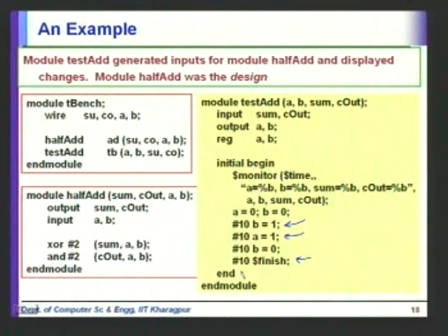Alright. Why do we have this 10 here? It is allowing the output to change for the last simulation step. When you are doing this with B equal to 0, A equal to 1, you need some time for the output to settle. Why? Because these gates have some inertial delay. So you have to wait until these gates settle.